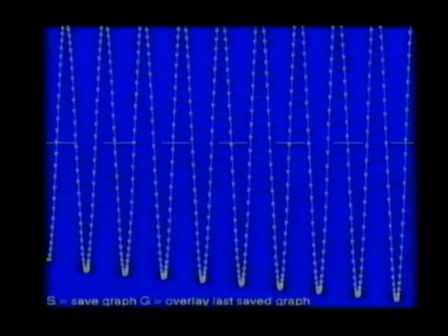So let's run through that again. That was a nice one. Proportional term of 40, integral term of 20. So that's going to get us up to that set point very quickly, but it's going out of control. No derivative term. There it is. That is clearly growing and going out of control. But if we add in a derivative term, it's damped it down enough to get it back under control, and eventually we will reach our set point.